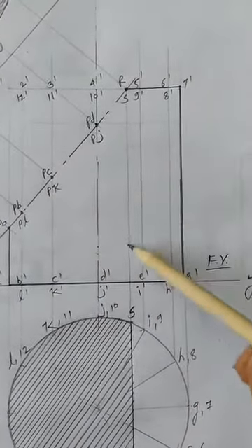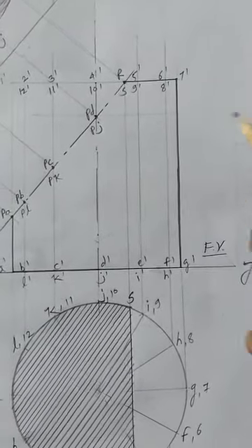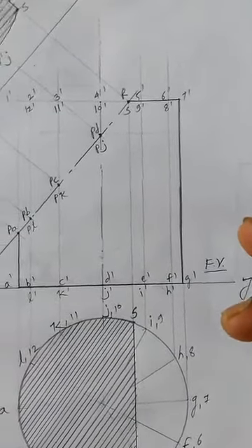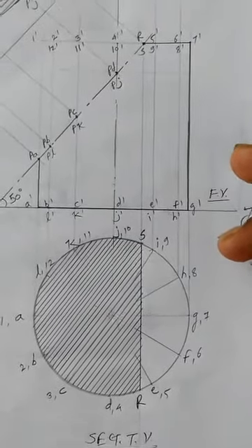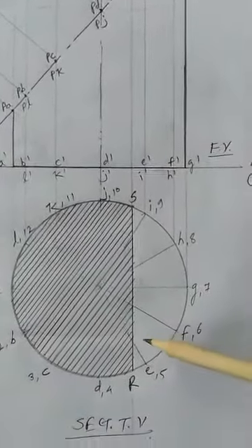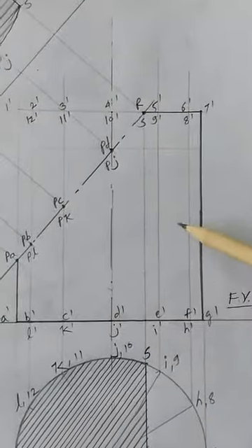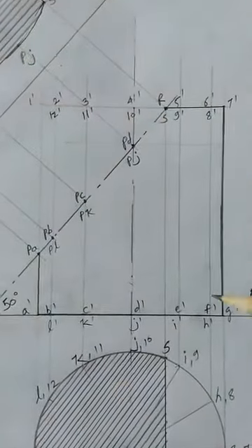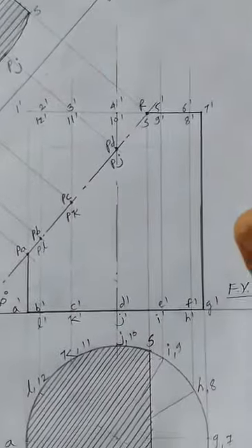Those generators are not actually there on that surface; when you touch the lateral surface, it is very smooth. For the sake of construction and projection only, we have artificially marked them over the surface, so those should be kept very faint. The left extreme and right extreme generators should be dark enough.